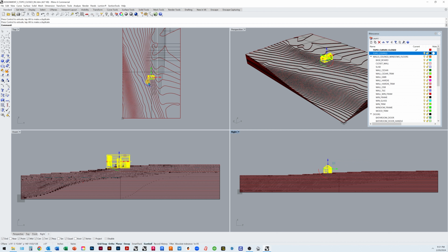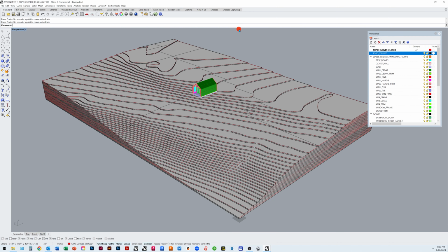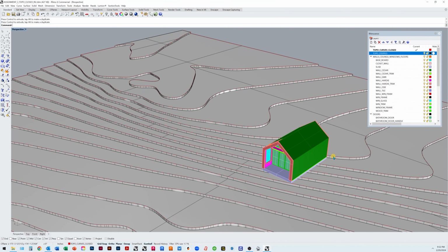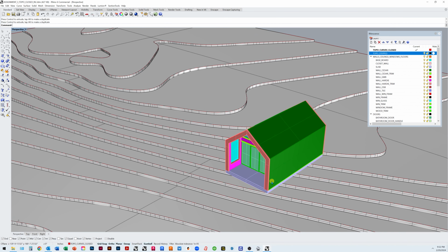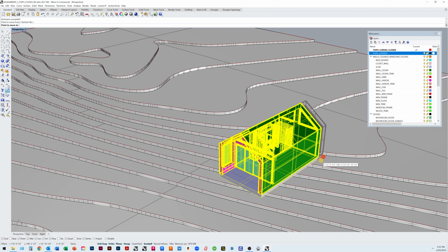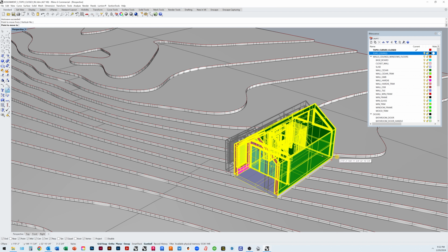So you can see here, it's where we want it horizontally, and then vertically, it looks like we're sitting generally within it. Okay, so once we have that, we can go into the model. This is where we want to make sure we have our snaps on, and we can snap and move our model so that it snaps to one of the points along the topography line.